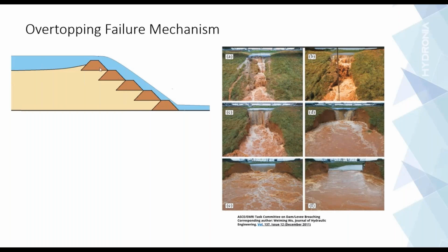What I'm showing here on this graph is actually a tailings dam. This is a typical upstream built dam that is not used that much anymore, but there are many dams that have been built in this way. So what happens in this type of construction, you have the need to create a deposit for the leftover of a mining operation. So you first build a dam like this, and then you fill this deposit. But you need more capacity, and it's filled already, so you build another dam a little upstream from the first one. Then you have a second deposit, and you fill it out, then you build a third dam, fourth dam, and so forth.